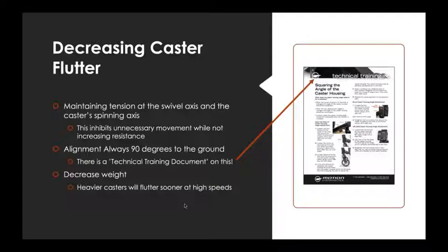And when you're sitting in, say, a living room on a hardwood floor, and you go to initiate a turn, if the caster stem bolt and the whole configuration is adjusted a little too tight, the casters tend to want to stick when you make that initial movement in the direction they previously were. So it can almost feel like somebody's holding your chair when you first go to take off each time. It can really be this weird, unsettling feeling. So that adjustment is crucial too in the performance of the chair.